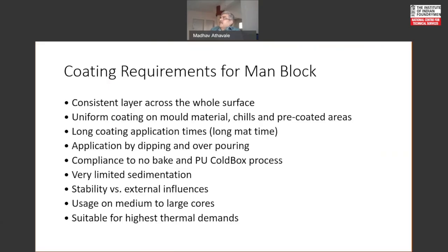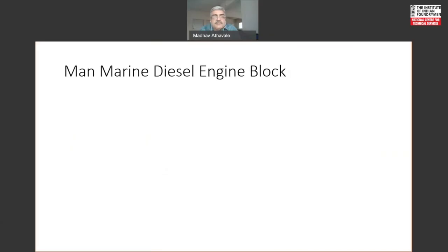As you can imagine, more than 100 tons is the weight of the casting. So section thicknesses are large, the size is large, so head heights will be large. So the fillers have to be chosen carefully, along with the way in which the coating will get applied. They have said in the case that the coating had to be suitable for dipping application as well as flow application, obviously by adjusting the consistency, but the filler combinations remain similar.